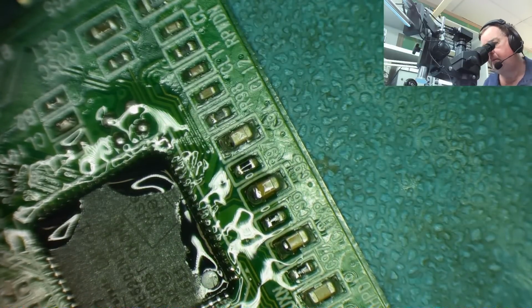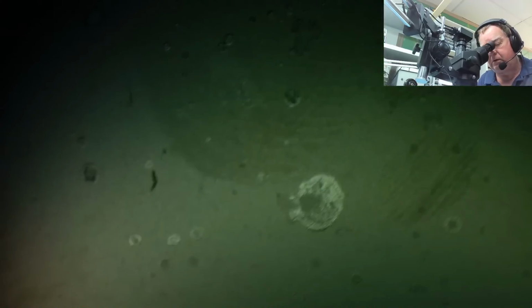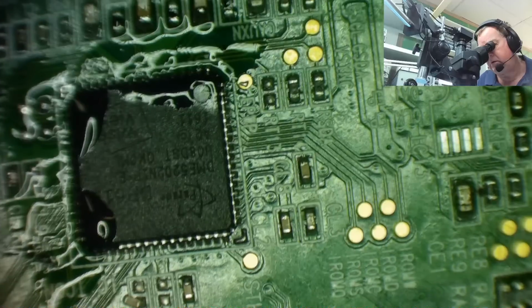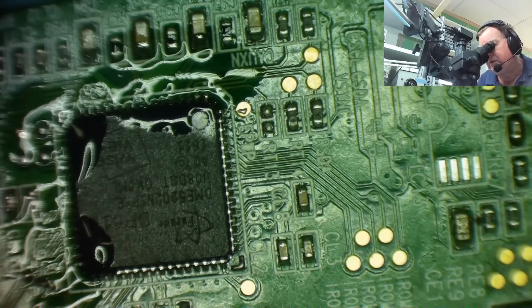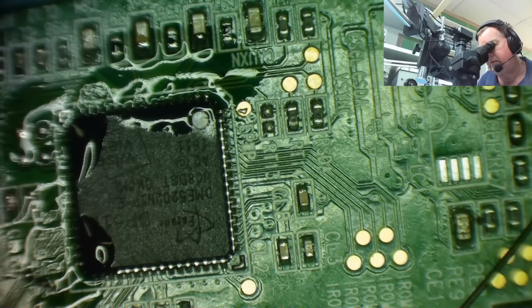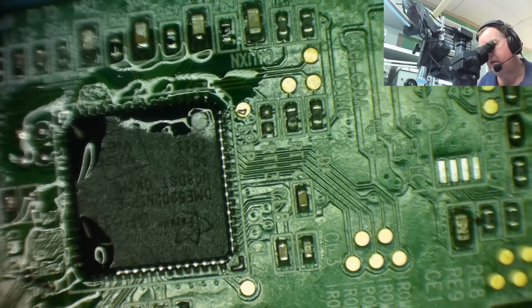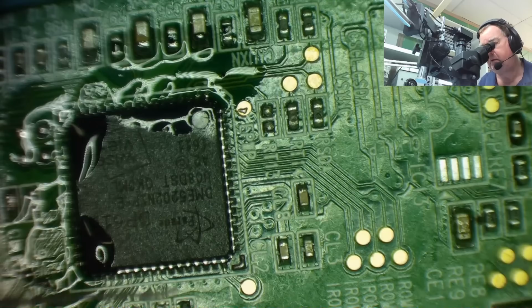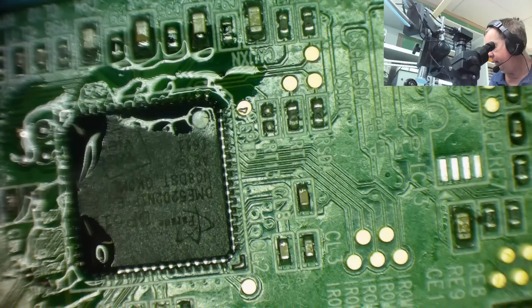Okay. That's that side. Let's go around for side 3 and let's have a look to see what we have on this one. Where is it gone? Okay. That one looks pretty good to me. Possibly that bottom leg. I've got a little bit of solder on the test point down here. That's not going to be a problem for any reason. Solder out of the way. Oh yeah, okay. Yes, I've got a little bit on that test point. This pin here may just need a bit of soldering.